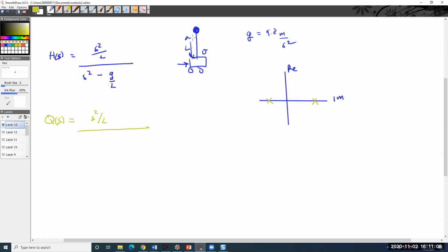So if I tap it and this starts wiggling, I want it to end up back at 0. Well, what does a high pass do? It detects the edge, and then it decays back down to 0. Now it's second order. It might do this, and probably we don't want that. So we don't want these complex poles too close to 0. All right.